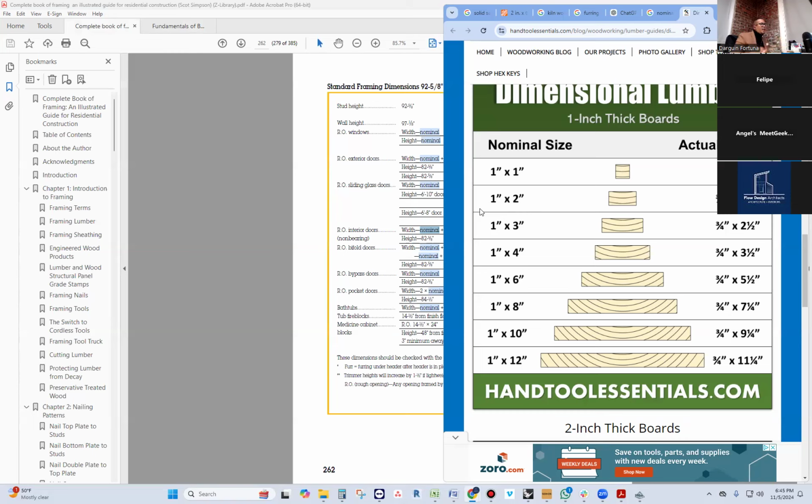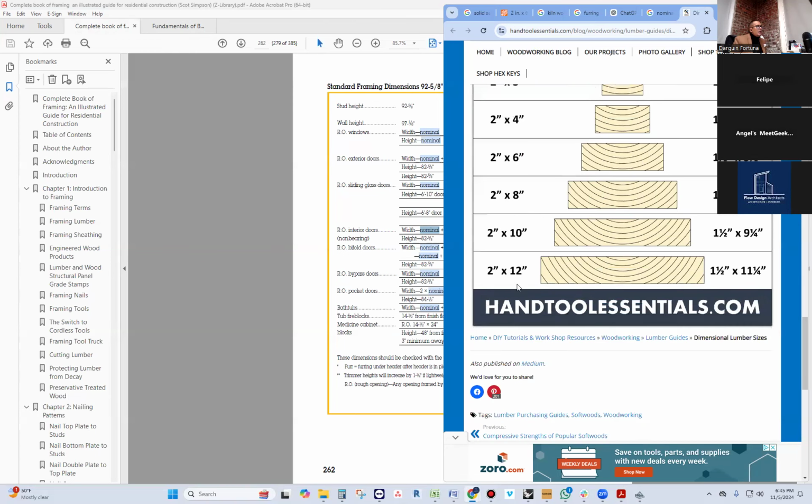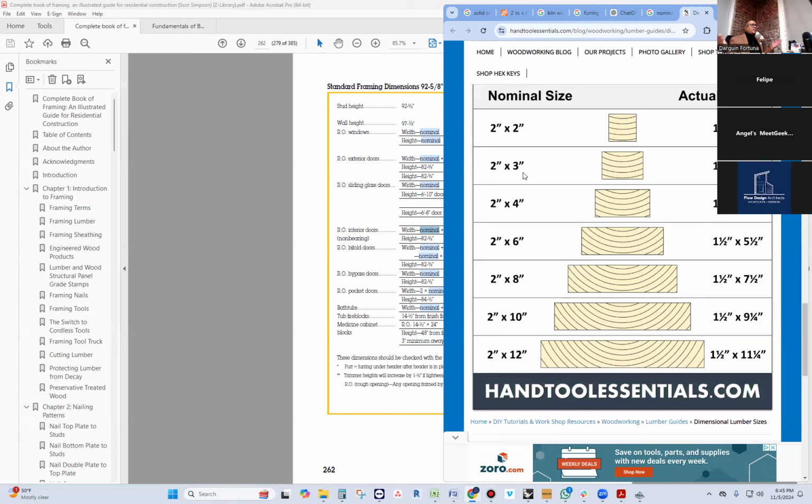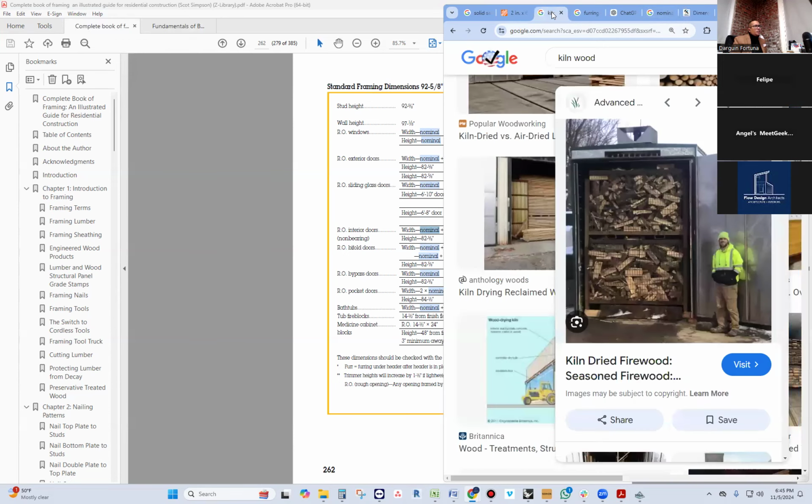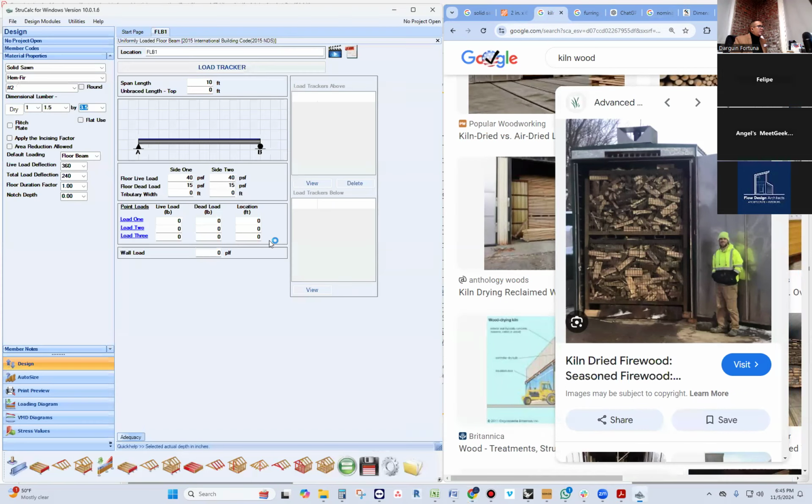So I hope you guys get that. This is the name of them, but you don't put the inches in it. As you guys know, wood gets cut by a very nice tool that cuts all the trees and makes all these lumber pieces, and they cut them exactly to be 2 inches by 8 inches. When you put it inside a kiln and you dry it, guess what? You lose a little bit out of each member. And that is the difference between the name, a 2x2, a 2x4, a 2x6, a 2x8, and the actual size.